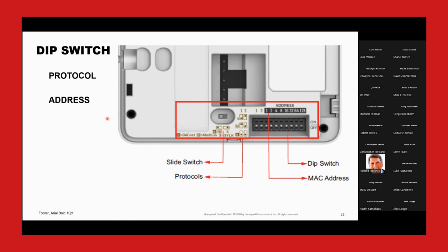So to answer your question, yeah, you can put it on a controller. Say again. How many of these sensors could we put on one controller? We recommend no more than 5 devices or 150 points per optimizer. I don't know if that's a hard number. I've yet to get a firm answer from Honeywell engineering. I asked them, is that a hard limit or a recommended limit? And the answer is yeah. I don't think they know either. So we spec the Modbus port for 5 devices, 150 points, whatever comes first.